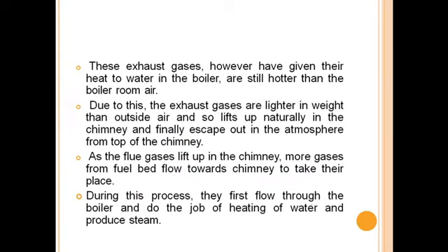And these exhaust gases, however, have given their heat to water in the boiler and are still hotter than the boiler room air. Due to this, the exhaust gases are lighter in weight than the outside air and so lift up naturally in the chimney and finally escape out into the atmosphere from the top of the chimney.